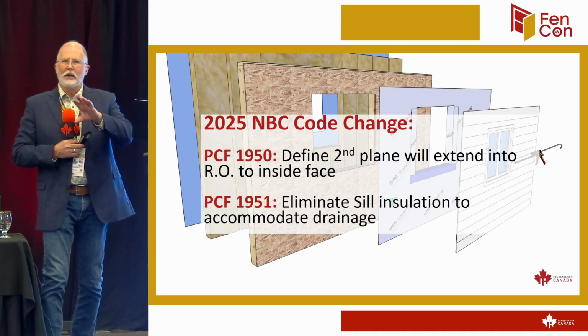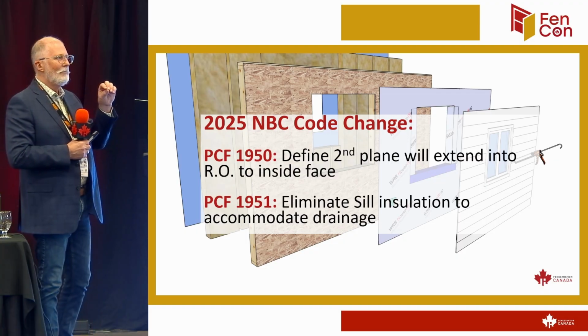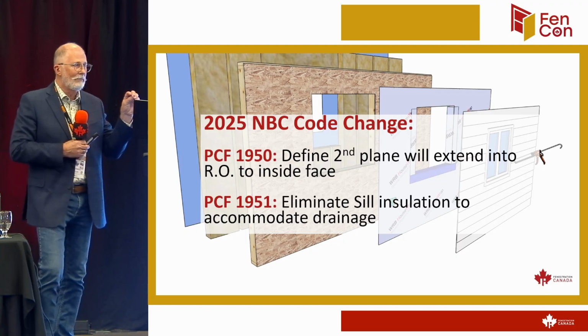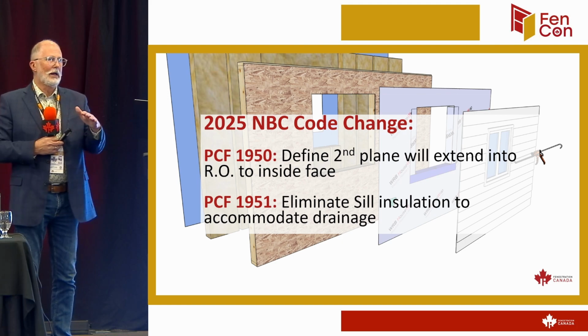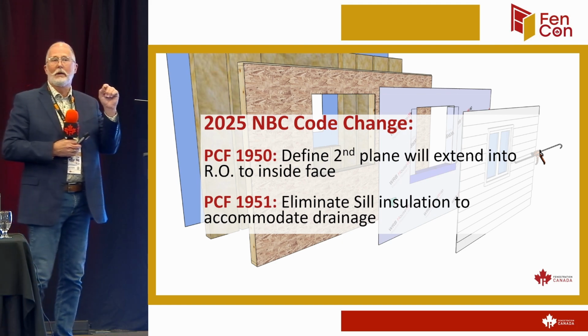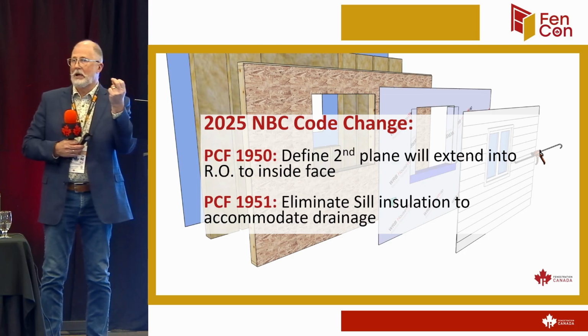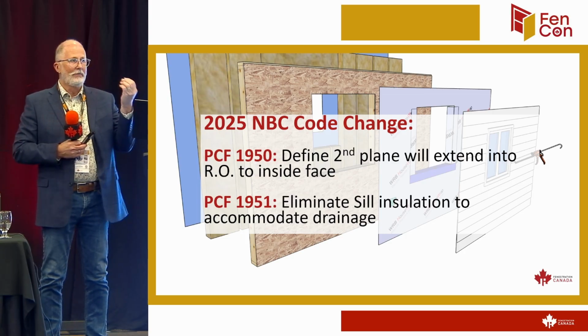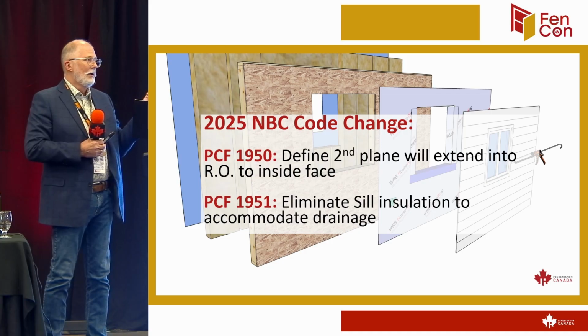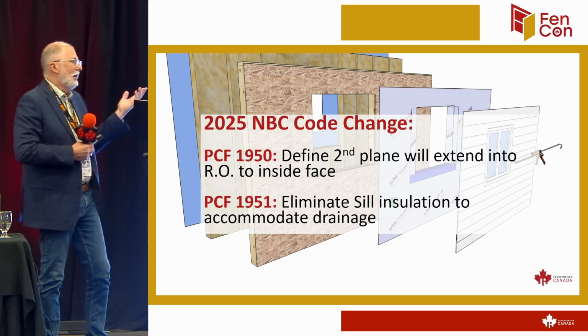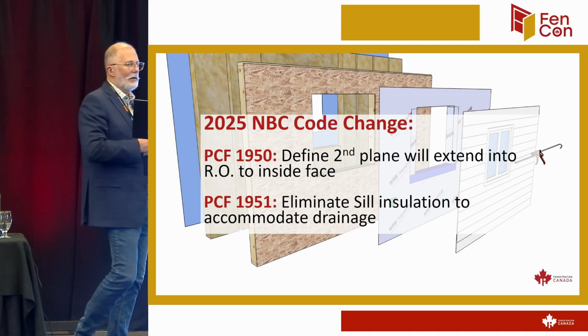When it's phobic, it's fear of, so it doesn't absorb. So a mineral wool or a stone wool will not hold that moisture and will drain it back outside. Plus, it gives you a lot better air tightness than a fibrous material. And a fibrous material, like a fiberglass, will just hold on to that moisture. And if it's sitting against a piece of wood, that's going to keep it wet for long enough that it's going to deteriorate and break down.